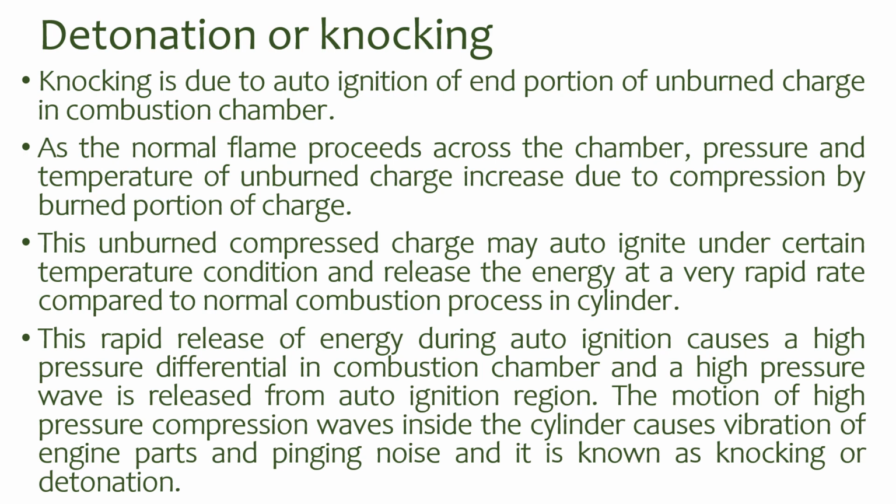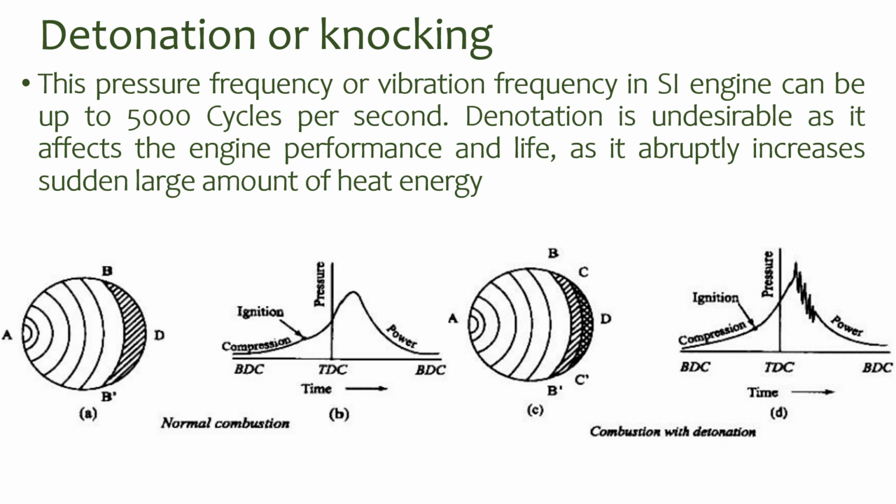This rapid release of energy during auto-ignition causes a high pressure differential in the combustion chamber, and a high pressure wave is released from the auto-ignition region. The motion of the high pressure compression wave inside the cylinder causes vibration of engine parts and a pinging noise, and it is known as knocking or detonation. This pressure or vibration frequency in an SI engine can be up to 5000 cycles per second.